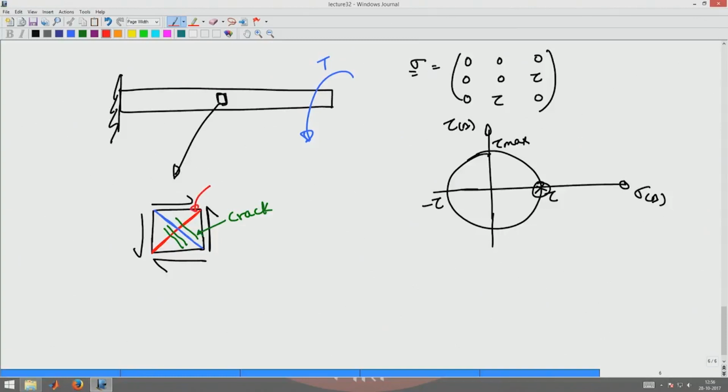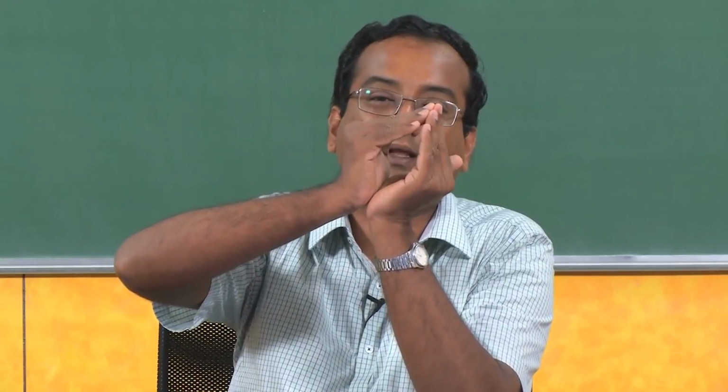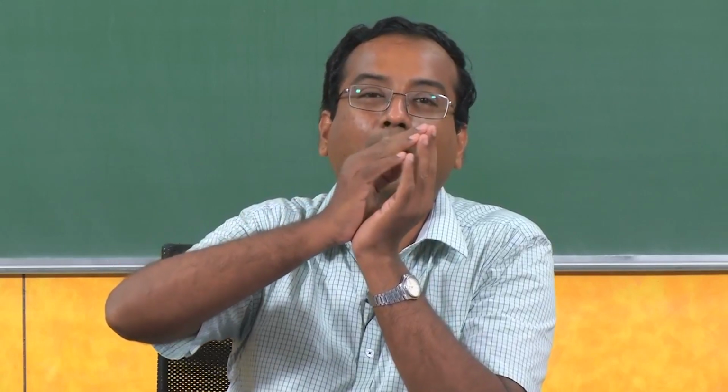This is the tension diagonal, this is the compression diagonal. So, the crack will develop perpendicular to the tension direction because tension causes the surfaces to be cracked. If I add tension along this direction, the crack will open up like this. That is, it will be parallel to the compression diagonal direction.